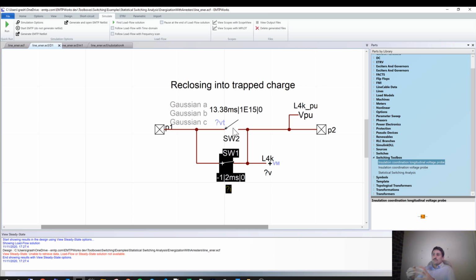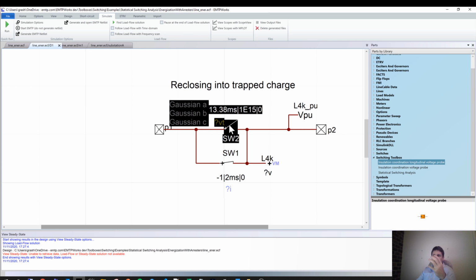Here you understand that when you simulate this process, opening then reclosing, whatever the closing time, the closing time is the one which varies, so you will change the closing time, but the beginning of the simulation is always the same. You disconnect and then you reclose. So in all the 200 simulations, the beginning is the same.